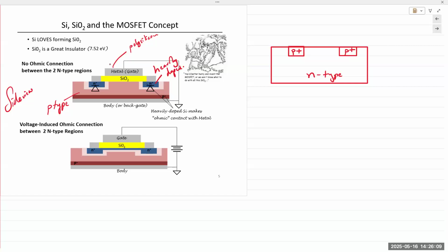Okay. So with P-type material, you have a heavily implanted N plus, and then you have an insulating material that isolates these two terminals. Again, this is isolating here, no contact whatsoever. And then you have some metal in the center. This metal is important to fabrication and the device. It's not important here for our understanding.